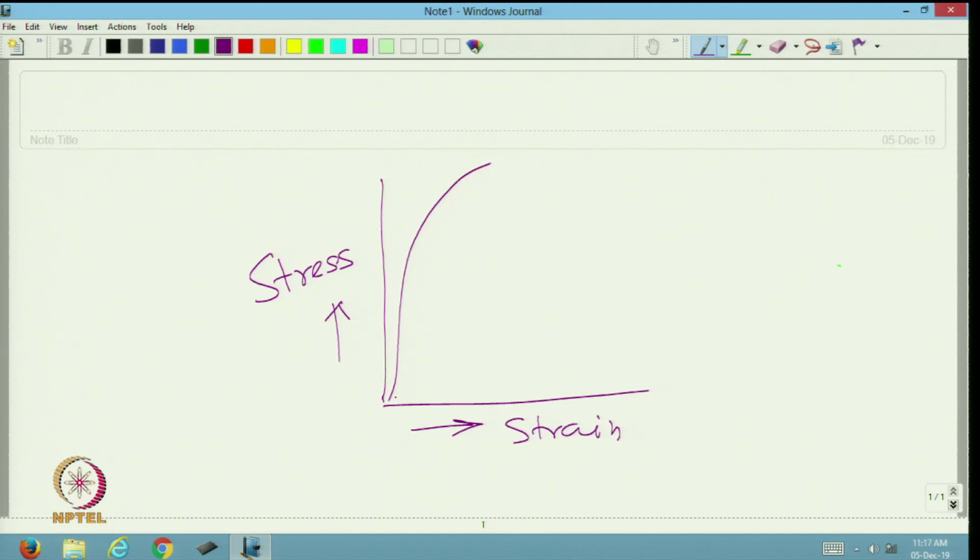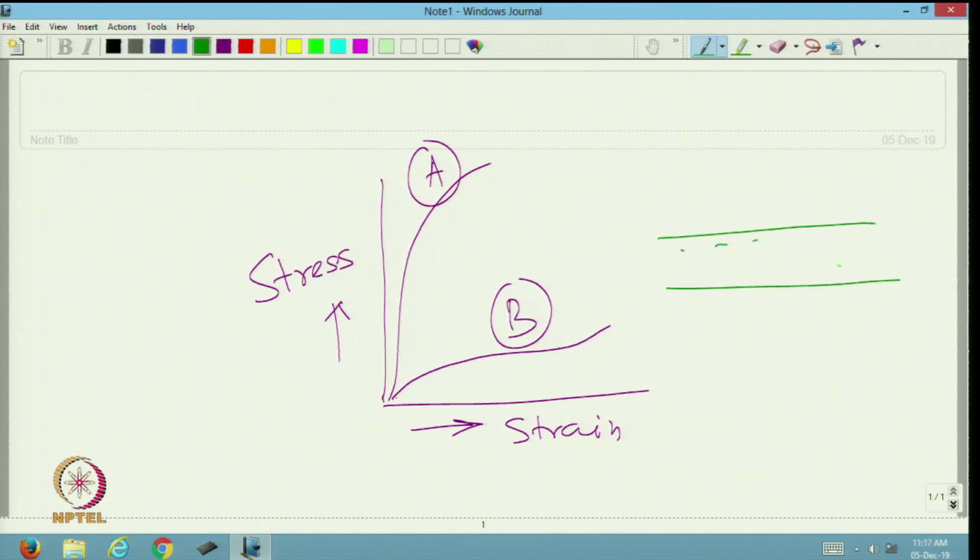this is one fabric and this is another fabric, A and B. Which one we should use for say reinforcement purpose or maybe geotextile stabilization purpose. So, this is the structure, soil structure. Now, we are using, these are the say gravels and we are using say geotextile for separation here. This is the geotextile.